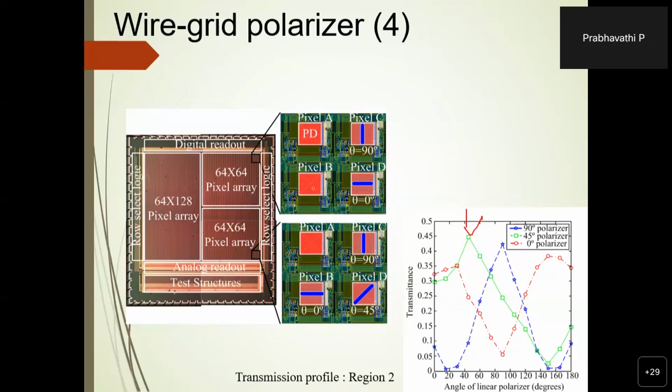Yes. So let me answer your first question first. HDR is high power, that is not correct. Most of the cameras that you buy off the shelf in the market consume high power because of the way HDR images are generated. In HDR, they capture low light information first, then the highlight information, and they combine those images. So there is a lot of processing happening in those HDR cameras.